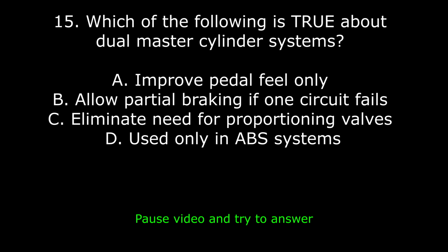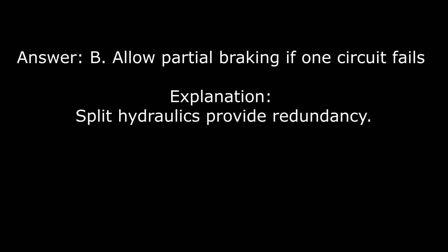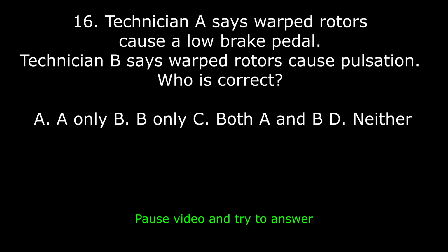15. Which of the following is true about dual master cylinder systems? A. Improve pedal feel only. B. Allow partial braking if one circuit fails. C. Eliminate need for proportioning valves. D. Used only in ABS systems. Answer. B. Allow partial braking if one circuit fails. Explanation. Split hydraulics provide redundancy.